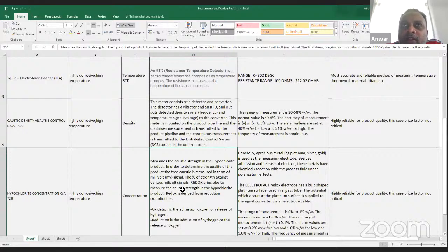The product will be recycled within the absorption column until it achieves the right ratio of chlorine gas and 20% caustic. This is cascaded with the stream of chlorine and also the stream of inlet caustic.